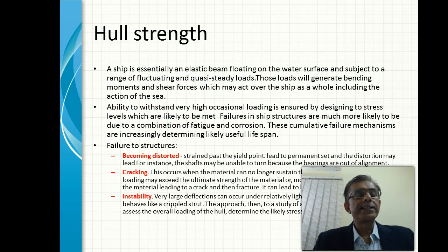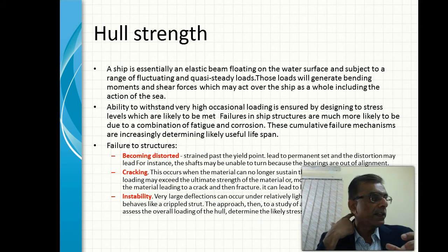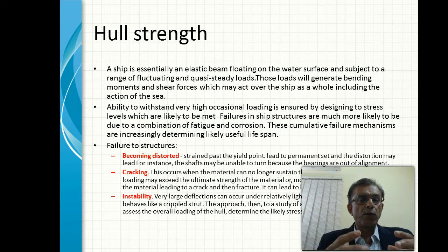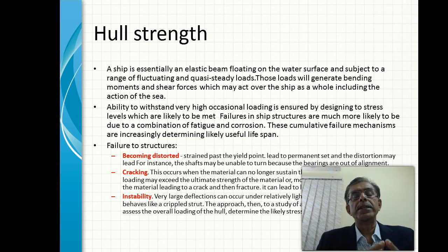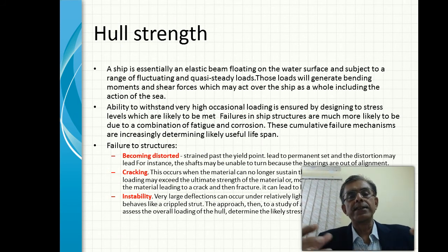Hull strength is a very important aspect, because essentially the whole issue of strength is that a vessel can become distorted. When a load comes that is more than what a steel plate can withstand, the plate buckles. It's a distortion issue, which simply means that the force has exceeded the yield point of the steel, or the material on which the vessel's strength bearing member has been designed. Or it could lead to cracking.